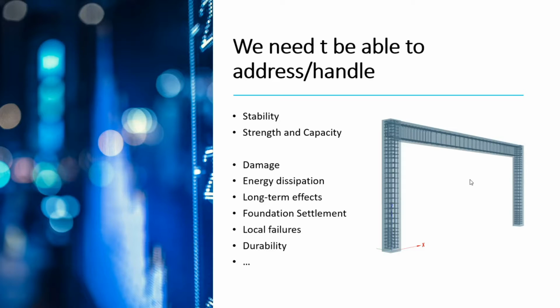We should be able to calculate the energy dissipation because of repeated loading or our seismic input. Long-term effects like creep and shrinkage, we should be able to handle those. We should be able to address foundation settlement and soil-structure interaction. We should also be able to look at local failures, for example, bond failure between steel and concrete, and crack formation and so on. And we should ultimately be able to say something about the durability of the structure. How long will it last? Or what are the things that will make it unusable in the long term? These are some of the considerations that we should be able to handle.